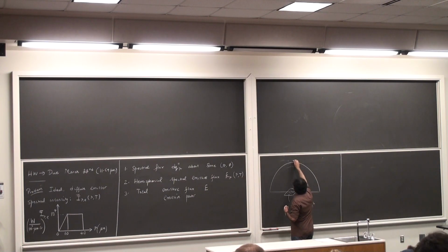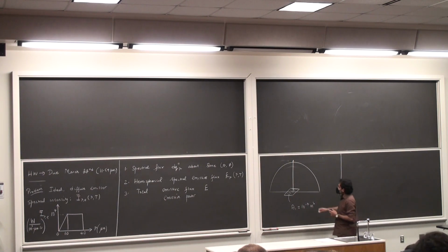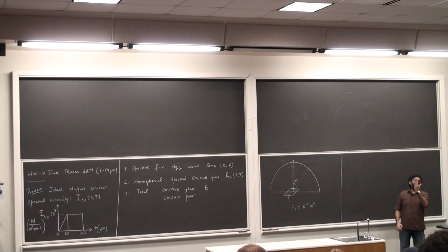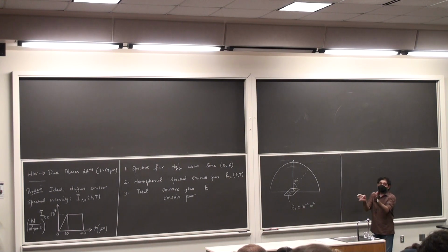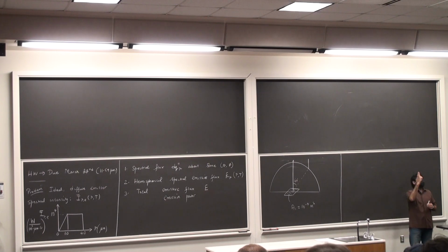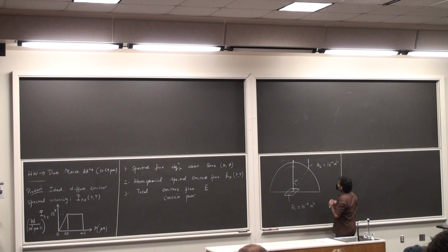So here is this direction, which is the area normal to the plate. Okay. And at an angle of 60 degrees to the area normal of this plate, there is another plate that is placed, but this plate is not placed on the hemisphere, it's placed at an angle to the hemisphere, so it's placed vertically here. So you're just seeing the front view of this plate, which is going to be a straight line. Okay, so this is another plate whose area is the same, so this is A2, 10 to the power 4 meters square.